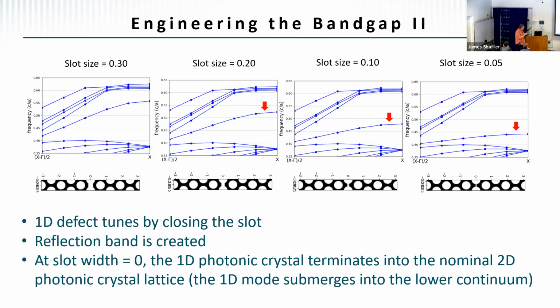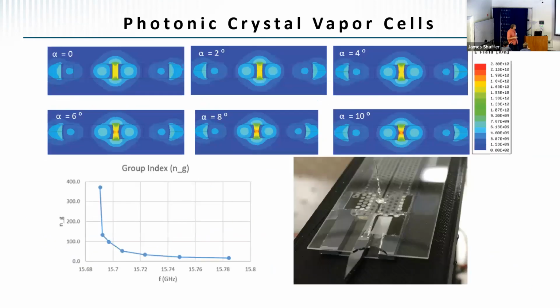This shows that you can actually change where that band gap is by changing the structure. So this is actually just manipulating the gap here, so changing the gap. So we do things like this to impedance match the RF into and out of the device, as well as do other things like make reflectors and such. In the building of this device, here's another prototype.